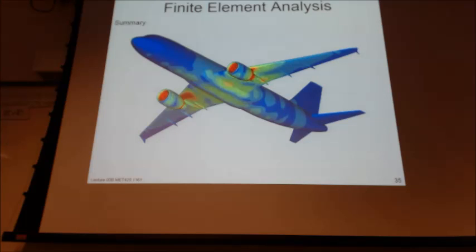What type of stress and what's its orientation? X, Y, and Z are principal stresses. We want to verify that the boundary conditions make sense. You're always going to draw a free body diagram. And you have to consider your confidence level in the loads. What's your safety factor going to be? Prior to obtaining your FEA results, you're going to attempt an analog calculation to provide you context and validation of your FEA data.